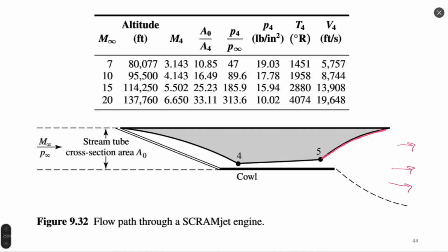Altitude is different for different Mach numbers because the engine works on a specific value of mass of air which enters inside the engine. So if we fly faster, we must fly also higher where density is smaller. So we receive a similar or the same amount of air inside the combustion chamber.